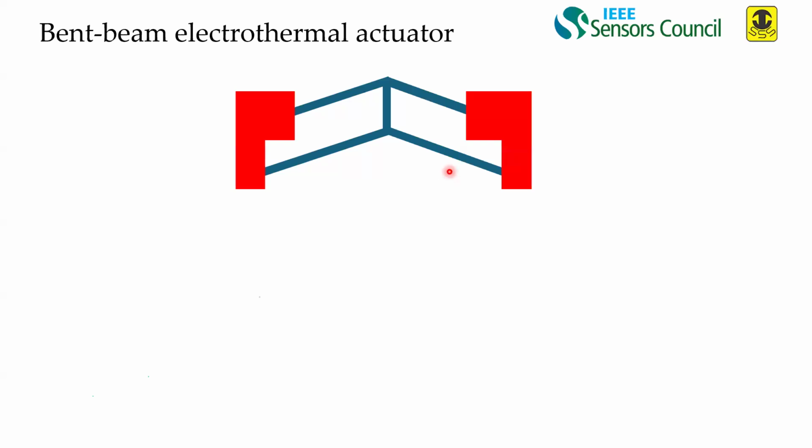Why? If you see the resistance formula, which is rho L by A. So here the length is small, right? Length is small, and your area is also small. So your R will be less. Similarly, P equals V square by R. So if your R is less, your P, or the heat, will be more, right? So in a smaller beam, heat will be more, so it will try to respond first.